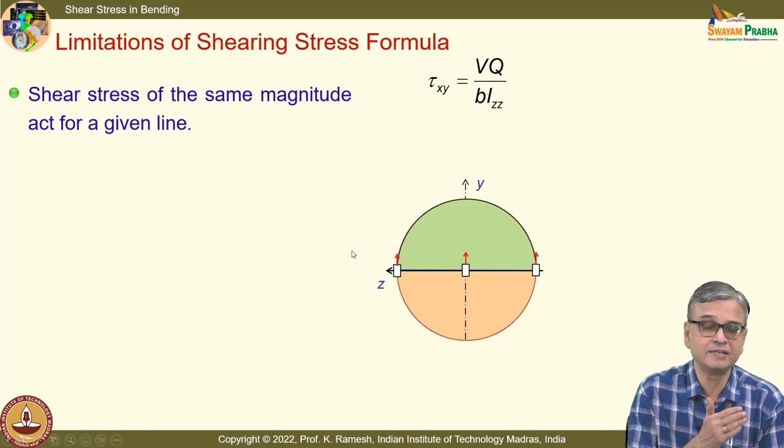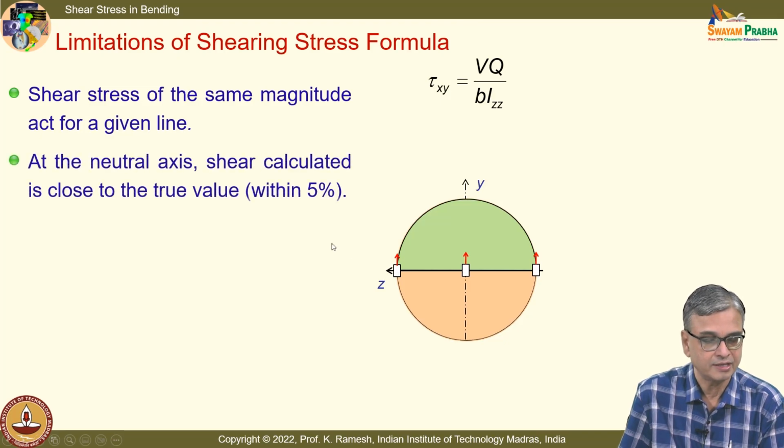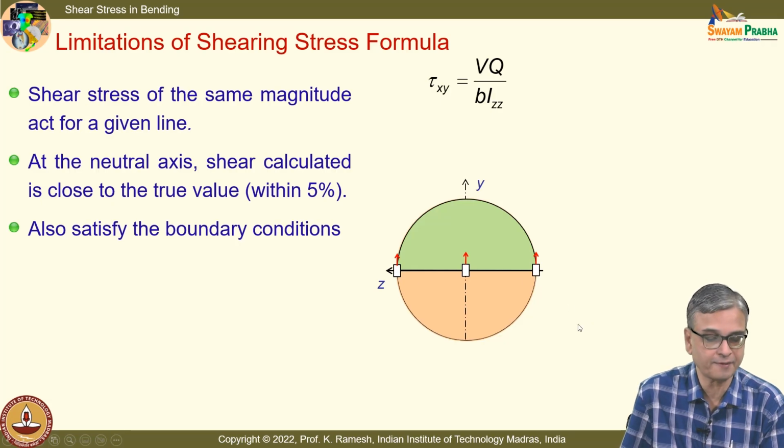We have discussed at length what free surfaces are, and you know from the loading of the beam, the complete outer boundary is free. Is the idea clear? That is a very important aspect. When I have shear stress acting in this direction, this also satisfies the boundary condition. There is no issue, because this is tangential to the surface at these points. There is no contradiction there.